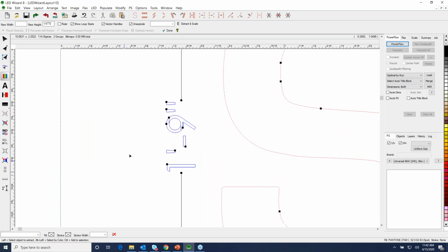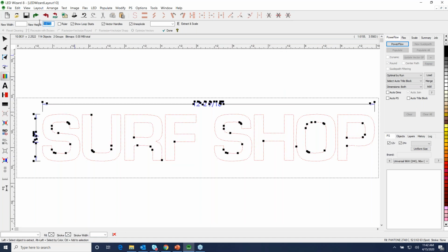The height here is 21 inches. Okay, I am going to use exploded, and I'm going to do 0.005. And I mentioned before that we have this value. What this value means is that one point will look around for another point that it might want to connect to, and it's going to look around at a distance of 0.005 inches. It's a very small distance.